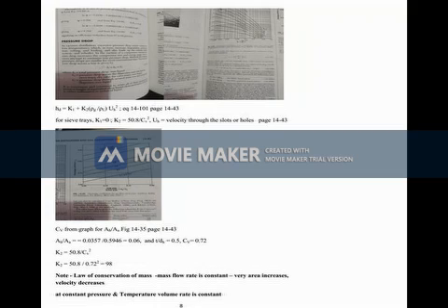Next we have to find the diameter of the column. How do you find the diameter? From the volumetric flow rate of the gas, because you have to take the volumetric flow rate which is higher. Usually the gaseous flow rate will be larger volume-wise. You get 0.83 meter cube per second. Then to get the diameter, we require the area.